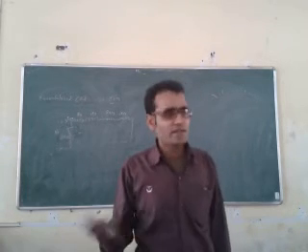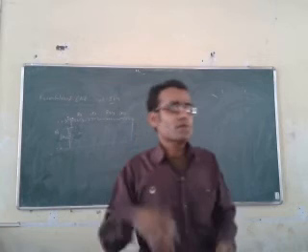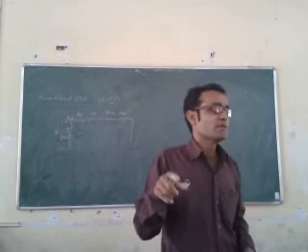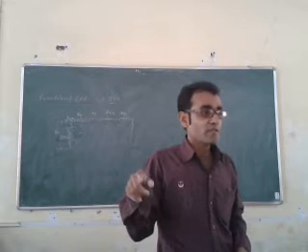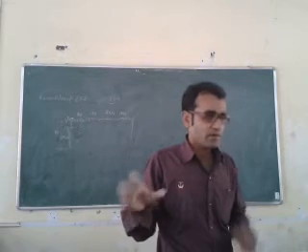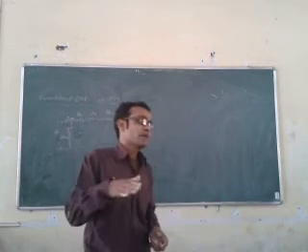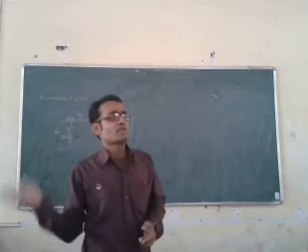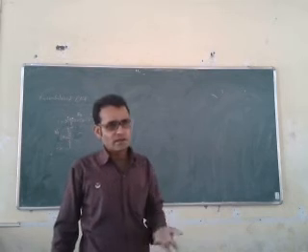I hope that you studied earlier: stator current is referred to the rotor, and rotor current is referred to the stator. There were basic equations: V1 by V2 is equal to I2 by I1 is equal to K is equal to N1 by N2. From these basic equations, to take V2 you multiply by K, and to take the primary side you divide by K, and you apply it depending on which side you are referring to, either from the rotor side or from the stator side.